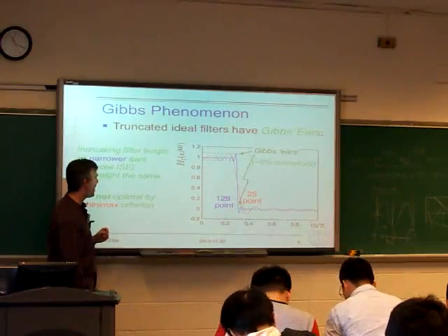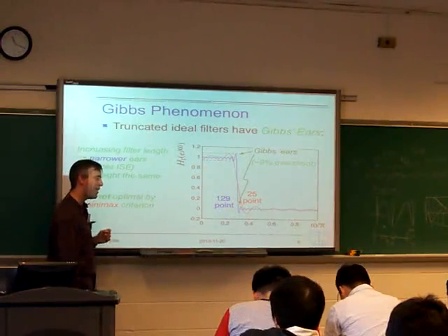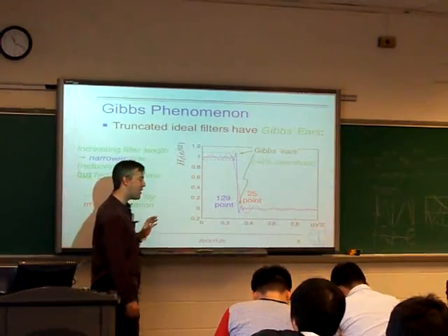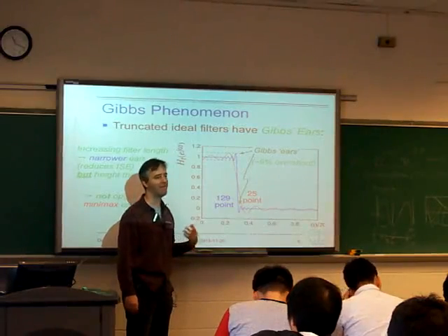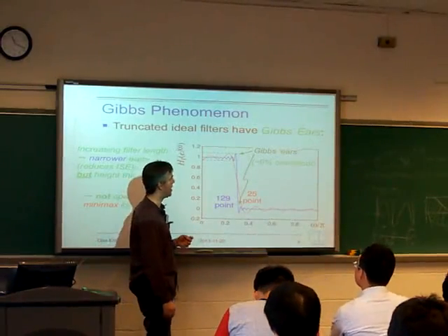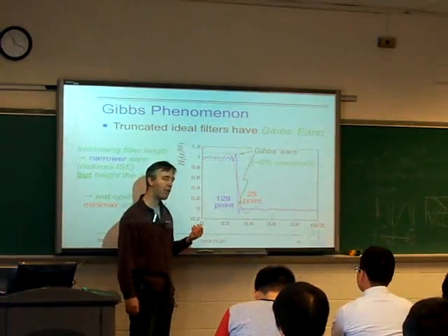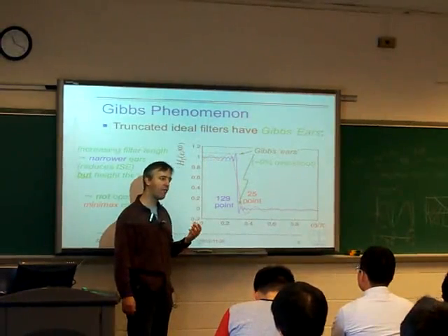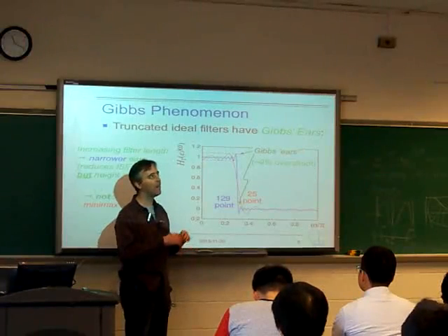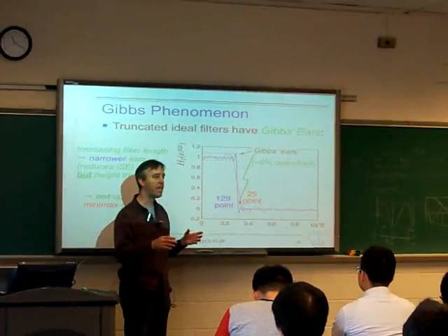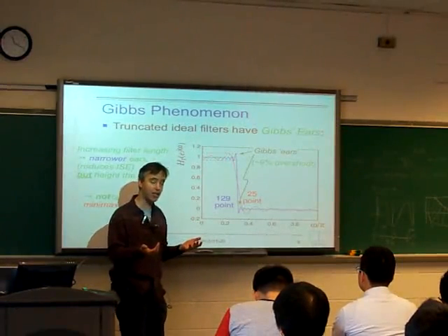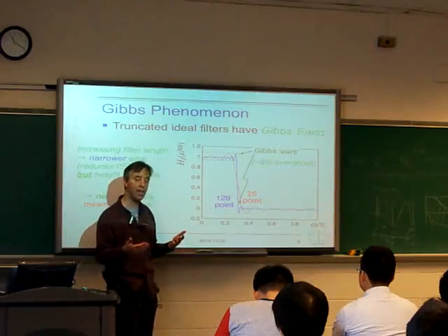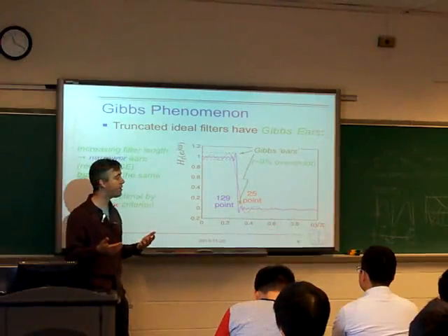And this is kind of a problem because we started out by trying to optimize integral squared error because that is the thing we can do very easily. But up until now, when we've been designing filters, what we've really tended to say is, well, I can't have an ideal filter, so I'll get the filter that has the least worst case deviation. I'm trying to minimize the maximum deviation away from the desired frequency response.